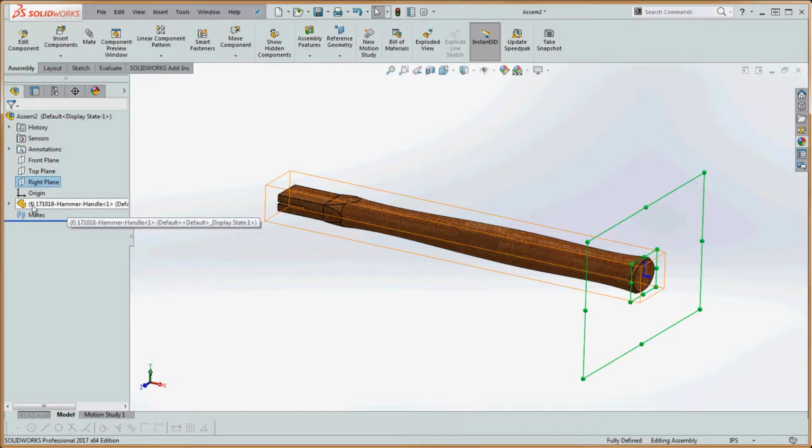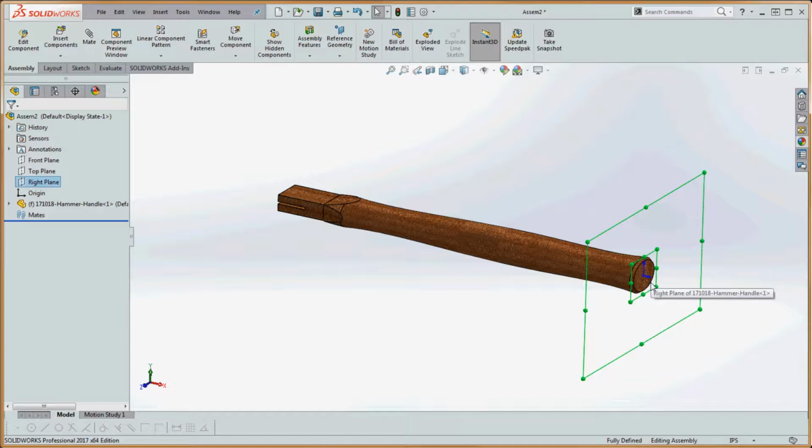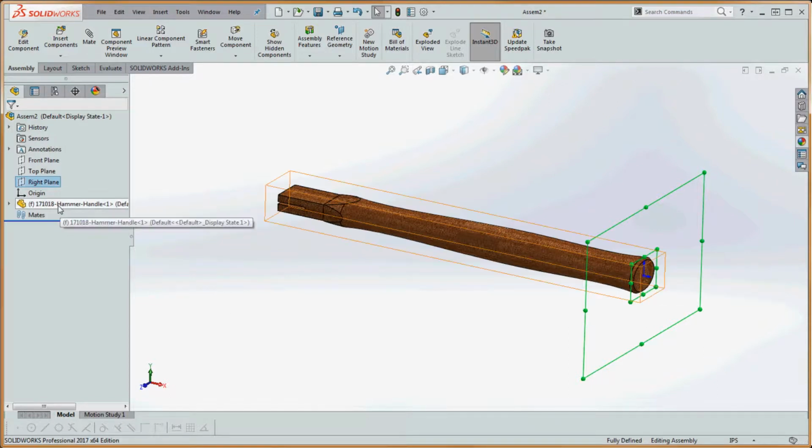But for now, that bracketed F actually means something. And this is another test question, another evaluation question. The first part you put into a SolidWorks assembly is automatically fixed. Not necessarily fixed at the origin. It is now that we went through the physical effort of actually putting the origins together. But the first part you drop in there,